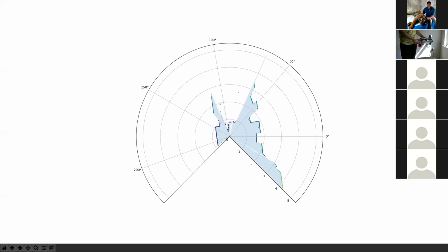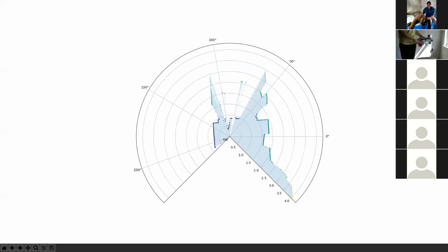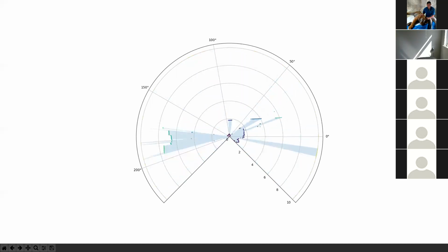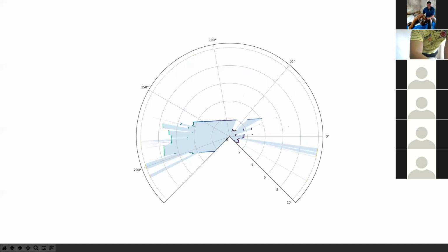For example, some of these LiDARs work with infrared light, and some windows are transparent to infrared, and some are opaque. So you might get points that hit the window, and then some that pass through the window. So you'll get really fuzzy results there. You won't get solid lines like you do on these walls around you. And you get the same thing around mirrors as well.